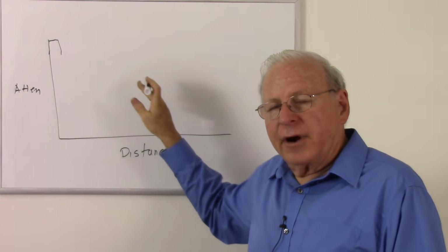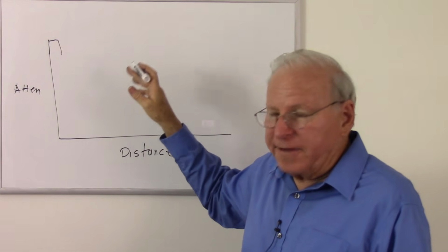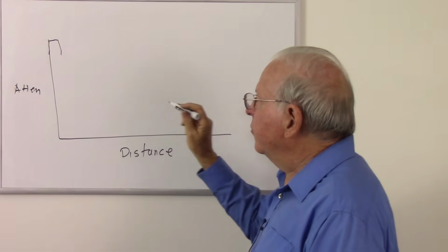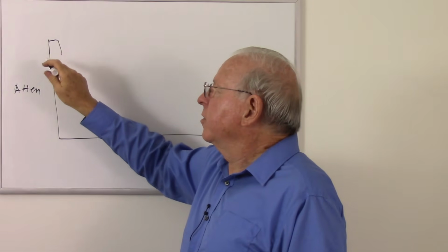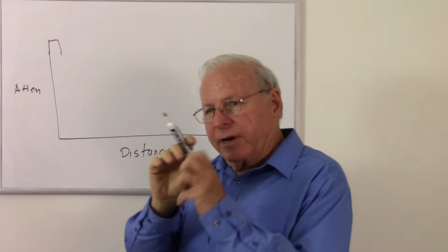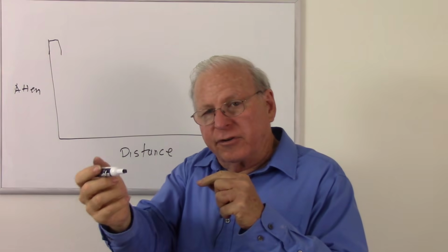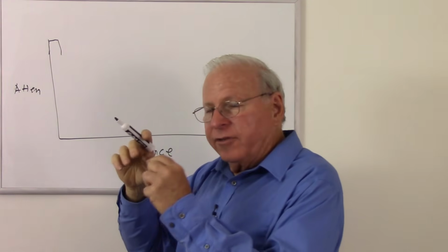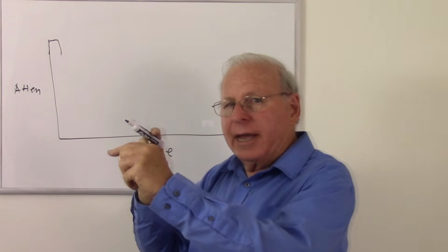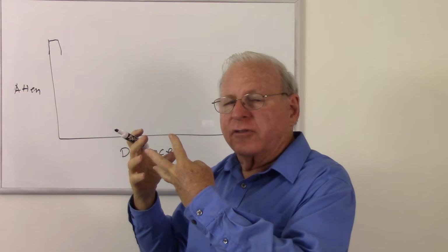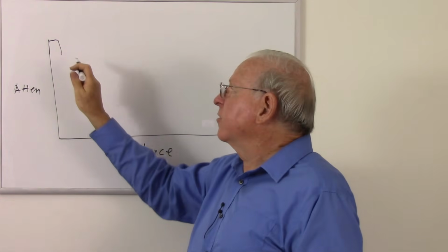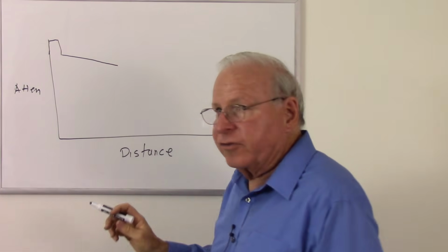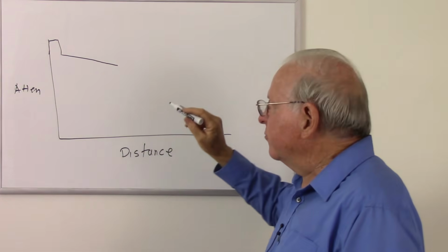So this is all happening very quickly. That light is traveling at perhaps 2/3 the speed of light in a vacuum. So it's going down very quickly, but we have this high-speed equipment that we can see what's going on. So the initial pulse, can't see what's going on because we're getting all that reflection back. We turn that off, and now we just see what's coming back as that pulse goes down the fiber. And so as it goes down, we see so much power coming back, but that power is attenuated as it goes down, so it gets less and less and less. So we see that our reflected power goes down with time, which equals distance because we know how fast that light is traveling.